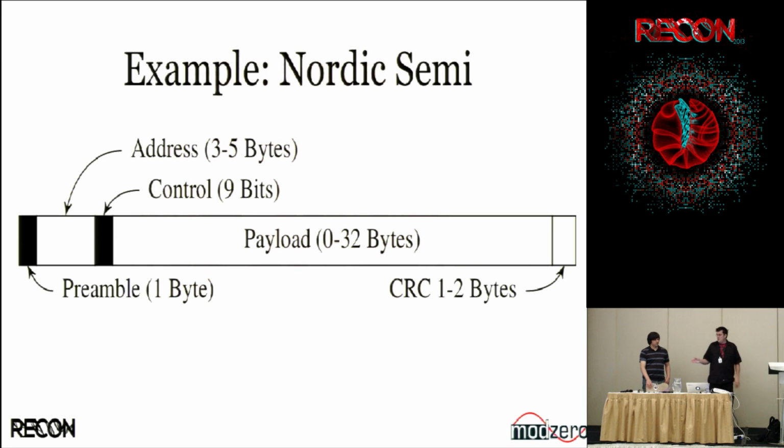What we can do now with an FPGA is we can just define a huge shift register. We shift all the bits into the shift register and match the preamble, for example, and then we can also just calculate the CRC checksum at the end. Even though we don't know the exact location of the CRC, using FPGAs, we have definitely more possibilities to match valid packets and capture valid MAC addresses.